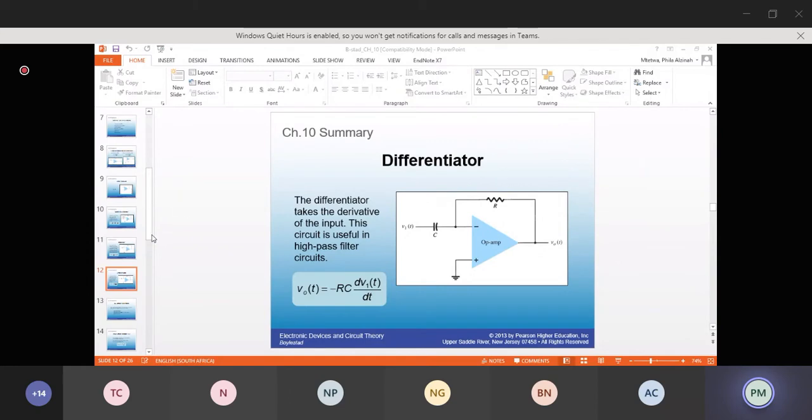Have a hang of what you mean by rectification. Remind yourself of that, as I told you in class: what makes the diode appropriate there as a rectifier is its conducting in one direction. After rectification, you get your capacitors to filter the signal, clipping off the peaks, causing the signal to be much smoother. But that's not the function of a capacitor. A capacitor charges slowly with time and discharges slowly with time, and based on that characteristic, it is applicable to use as a filter.